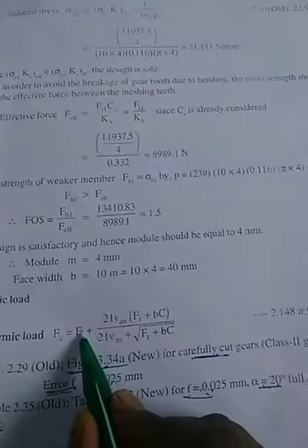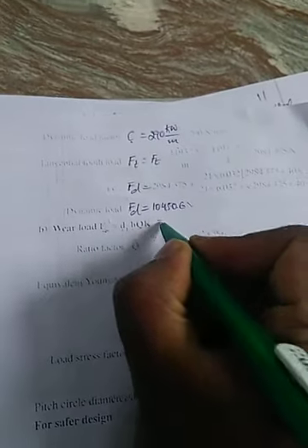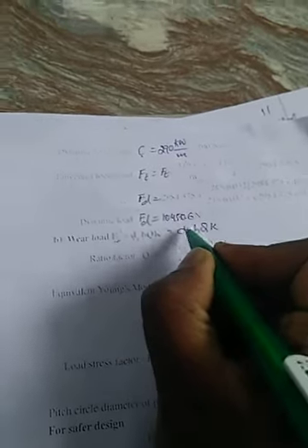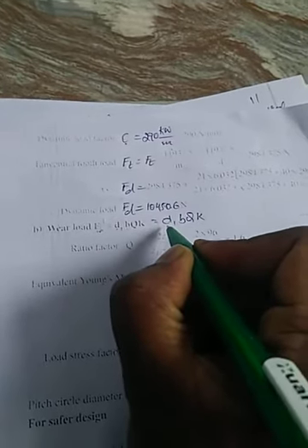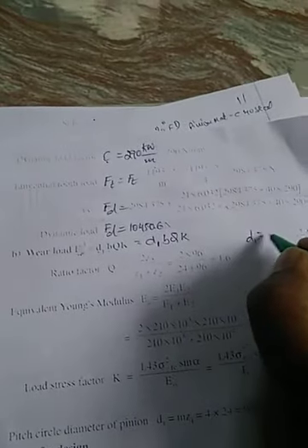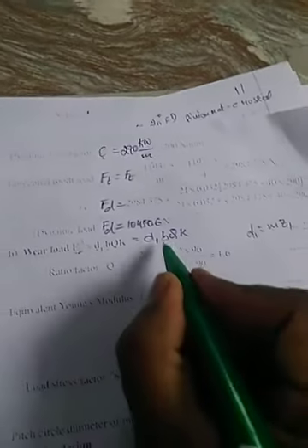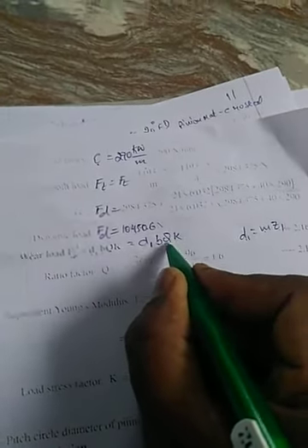Substituting the value of Ft, the value of Vm, B, C, everything, after simplifying we will get Fd equal to this value. Next, after calculating Fd, we consider the wear load. The wear load formula is Fw equal to D1BQK. Here it is always D1. It may be pinion or gear, whichever is weaker, we always consider D1 only. As you know, D1 is equal to M into Z1. You already know M and Z, so you can calculate D1. B you know, but unknown are Q and K.